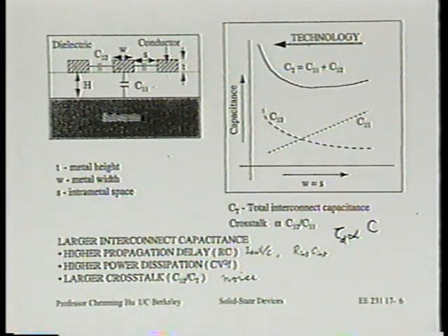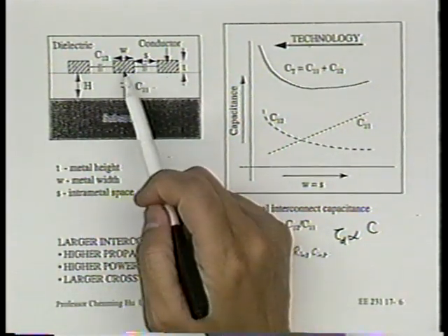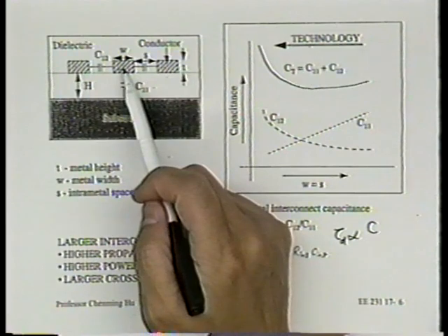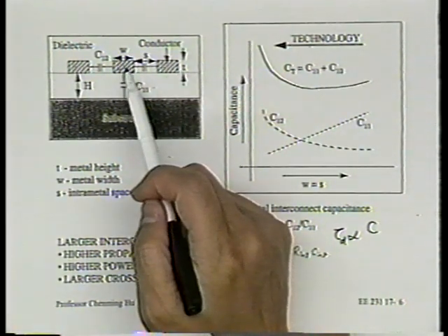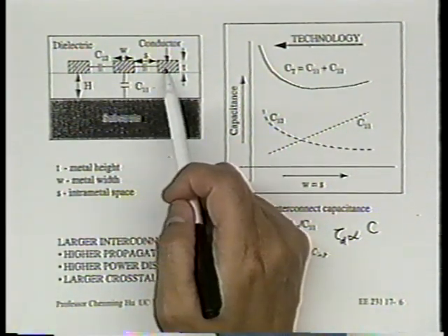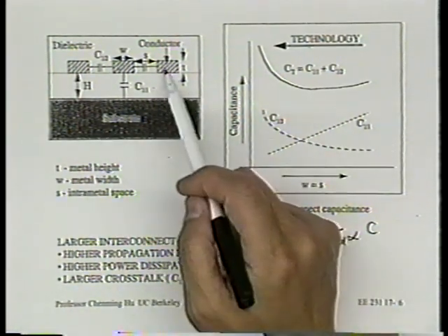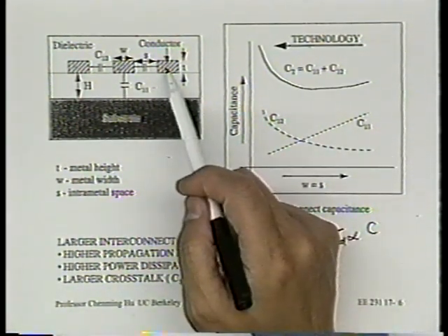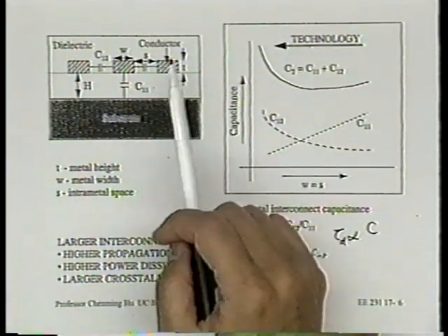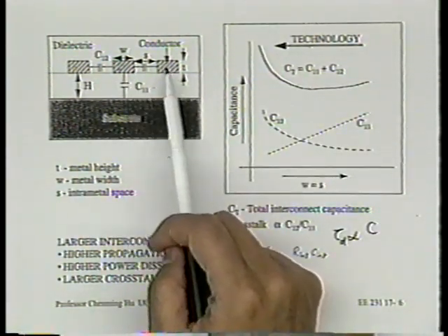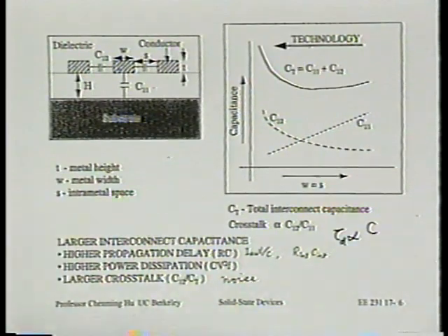So that's always bad. There's a third consideration, noise, or you may say crosstalk. That is, if a signal is applied to this middle wire, it's also going to capacitively couple to its neighbor, right? So to its neighbor, there's going to be noise. If noise is too large, it's going to perhaps give you a wrong logic reading. If noise is that large, it may have an impact on the delay time of this